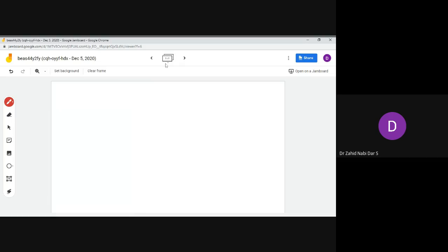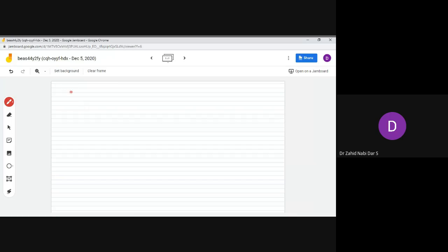Now see, one more important thing where most of the students make a mistake. When we write this power in terms of phase quantities, it is 3 V phase I phase. Now suppose the machine is connected in delta.